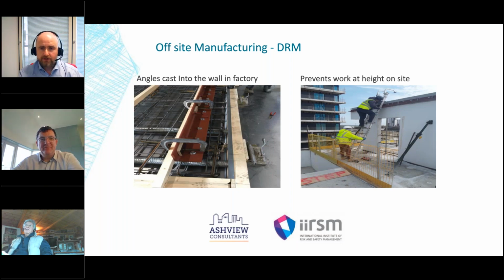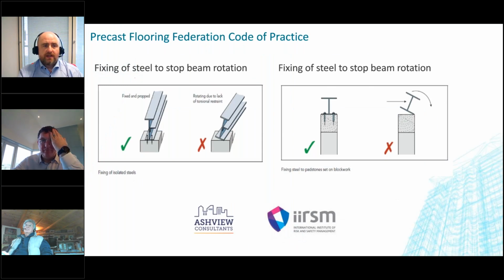Yeah. So again, that's reducing the risk for the site teams. So this is actually out of the precast flooring code of practice. It's showing beam restraints. The risk in this is if the precast installers, the guys installing it, load out one side of the beam.